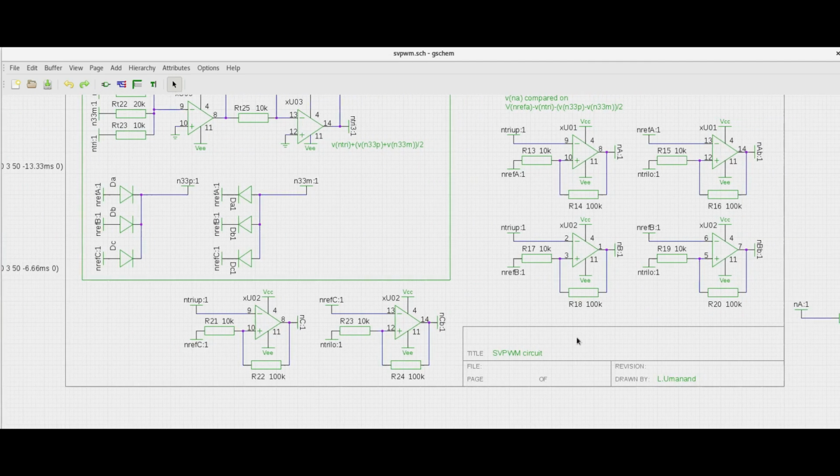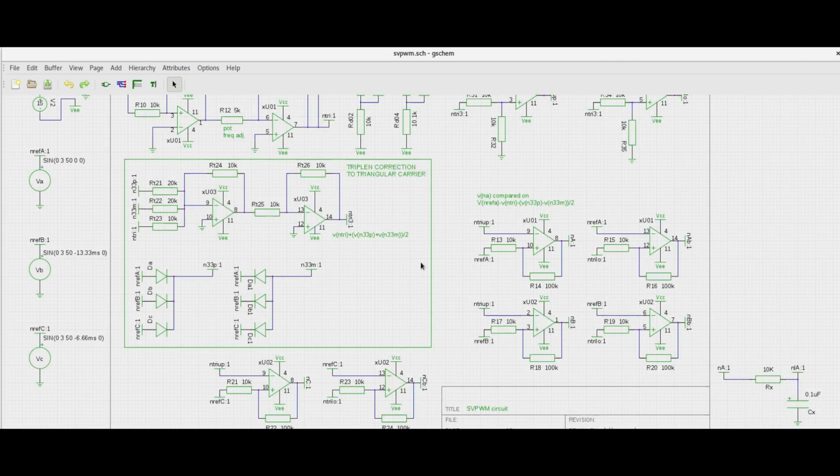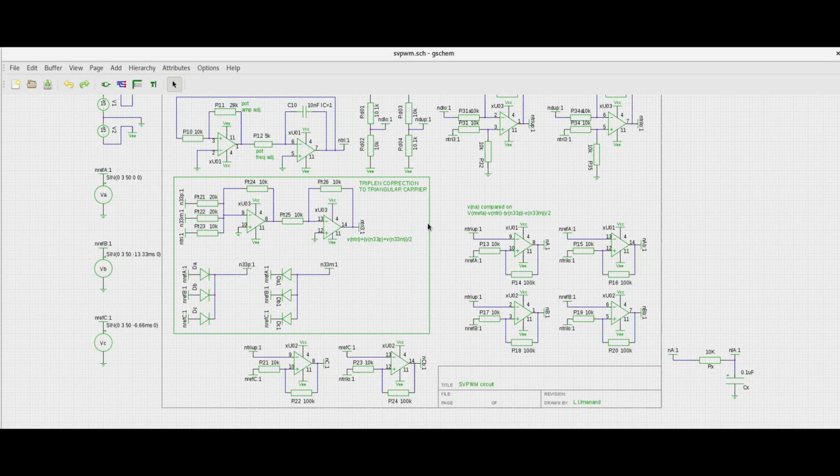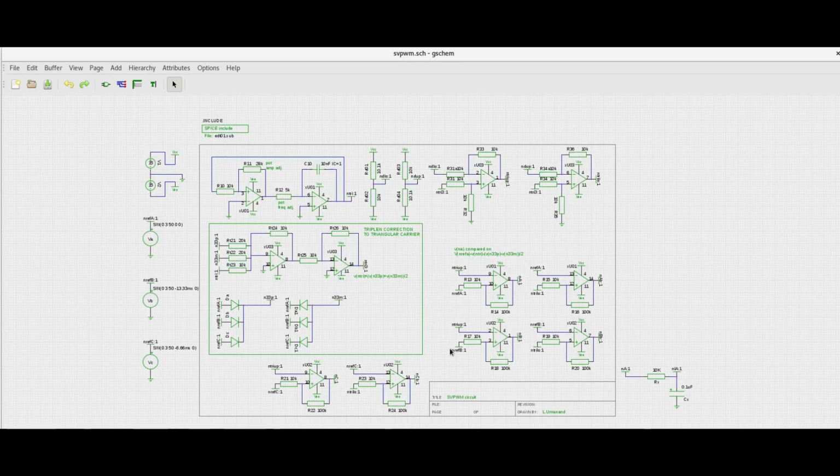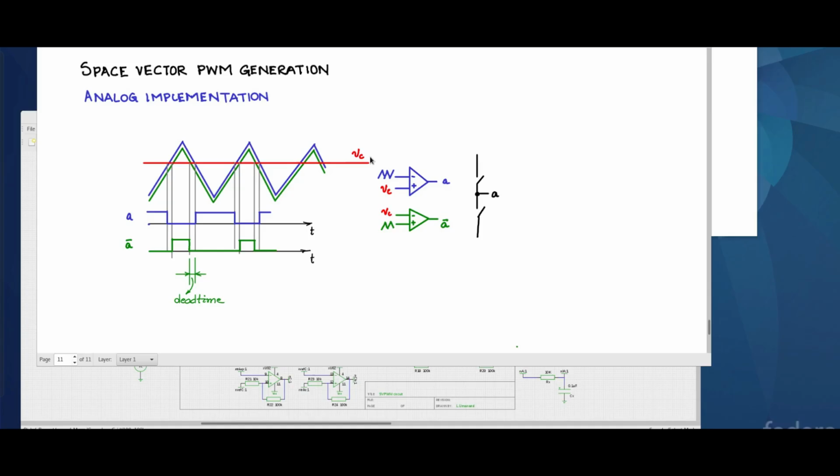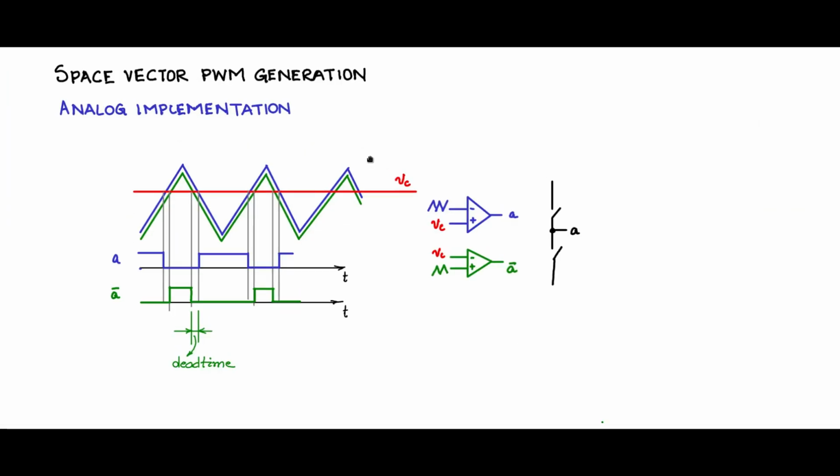Now in a normal PWM, this is fine. Sinusoidal PWM, this is fine. But in a space vector PWM, a third harmonic is injected. Now why is a third harmonic injected? Consider this timeline and signal. I have this time axis, and I have these extreme limits. This is 100% modulation. These two limits are indicating 100%. A sine just touching this line will give you 100% modulation.